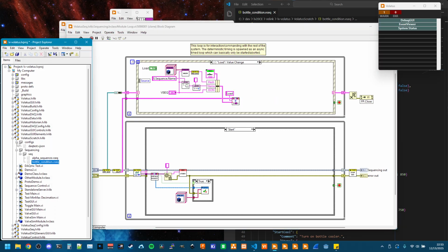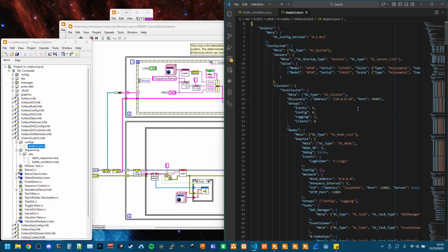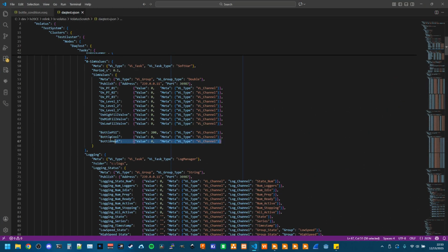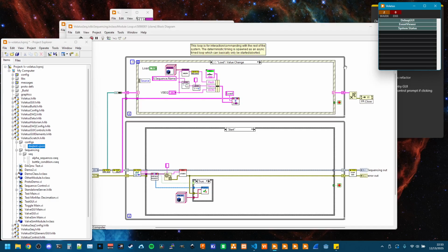Additionally, with this setup, if we take a look in the rest of the system config, I've added these 3 simulated software variable channels so that we can have a value we can poke as the process value that's looked at for this sequencing, and then 2, I'm going to call them output channels, so we can tell what mode it's in in our GUI. And in the real world, these would be tied to heater enable or cooling enable.